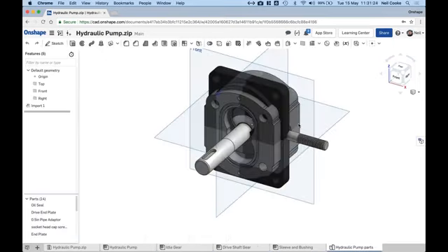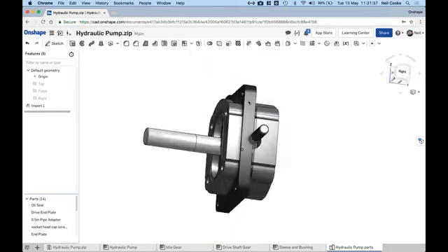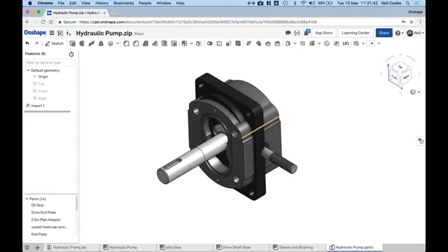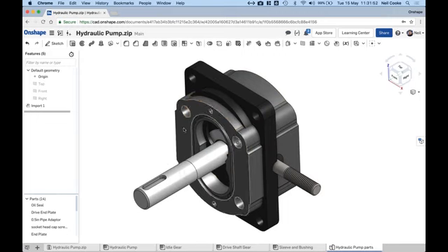But this will sometimes confuse people when they look at it. So this is the part studio, which is containing all the parts. Now, all of them have actually been added to the origin in this part studio. Okay, so you can see they're actually not in their relative positions. So that's the difference between importing it as just a flattened part studio as opposed to having an assembly structure in there. However, if you do make changes to these, of course they will update in the assembly.